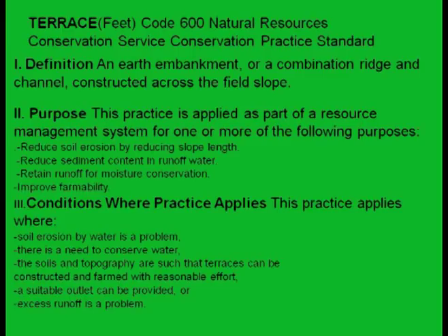I'm going to ask a question here. I want you guys to look very closely at these orange flags. Are those orange flags in this line, following behind me and the guy with the stick, going uphill, downhill, or perfectly on contour? I'm only taking 3 answers. Okay? You got it. These flags are actually going downhill at a 1% slope. Looks to me like they're going up, doesn't it?